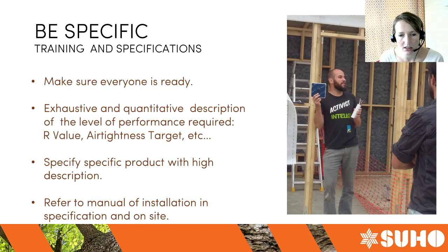There is also a real role in having a good specification set up that shows the targets and gives clear information about what we aim to do with the building and how we achieve it by using this or this material. So having really tight specifications about the products will help. If not asking for a specific product, it is really important to give a maximum of descriptive information about permeability, reflection, weatherproofing, all sorts of aspects that will act on the envelope.